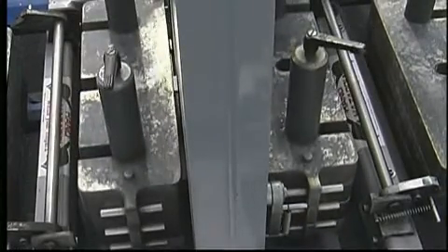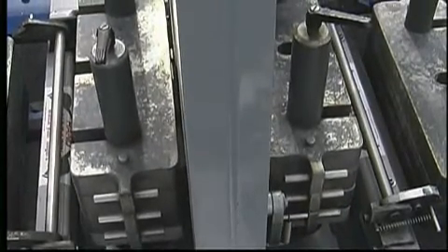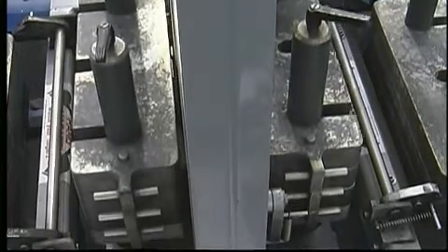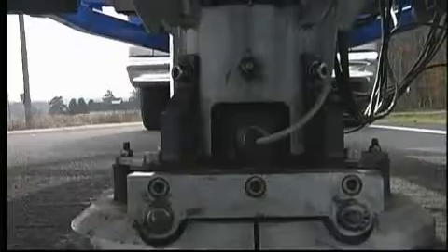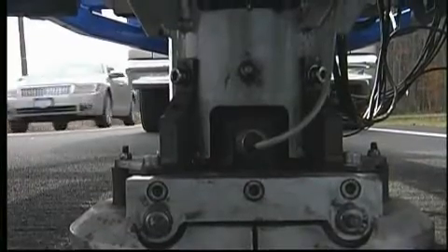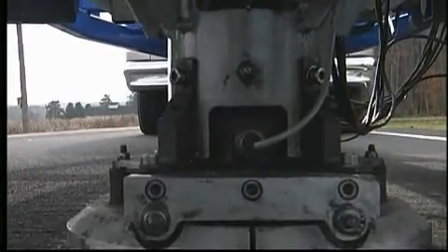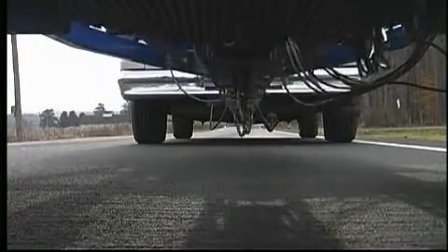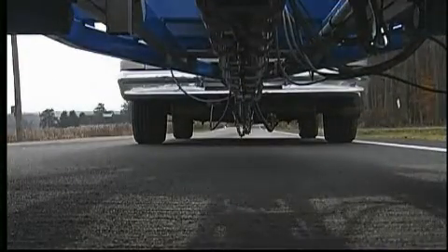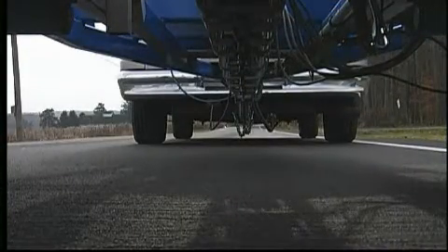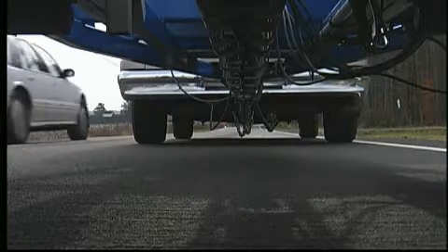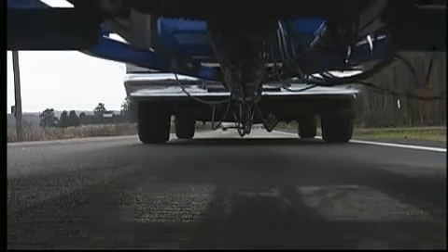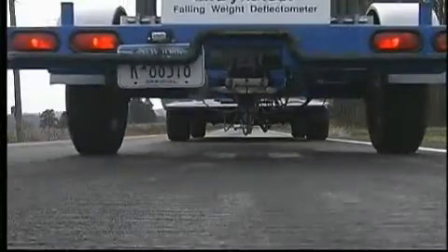It is critical that the data from the FWD be as accurate and precise as possible. Errors in the data will lead to errors in the pavement analysis. Without calibration, the bias error of an FWD could be as large as plus or minus 2% for each sensor. It is important to reduce these systematic errors in the deflection and load readings as much as possible. During FWD calibration, we can reduce the bias errors to about 0.3%. This greatly improves the quality of any pavement analysis.